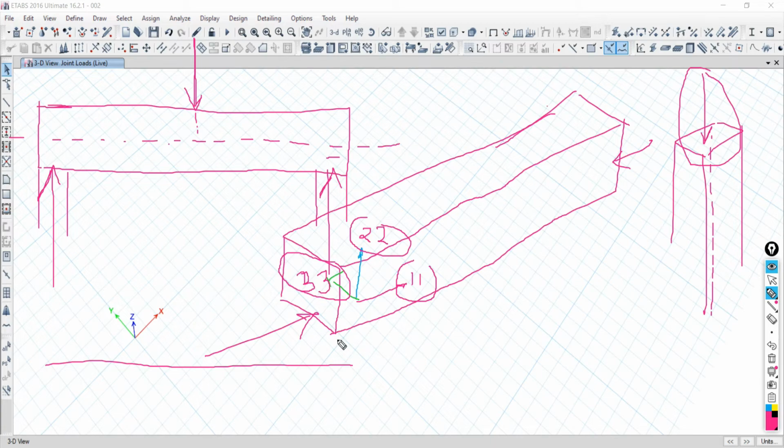You might solve the example for finding out the shear force diagram. So the shear force diagram for the beam will be like this. If it is simply supported and point loaded, the shear force diagram will be like this. Am I right or wrong? It changes at midspan. So it is having the shear force diagram, and under the application of this load and due to this shear force, there will be development of shear cracks like this.